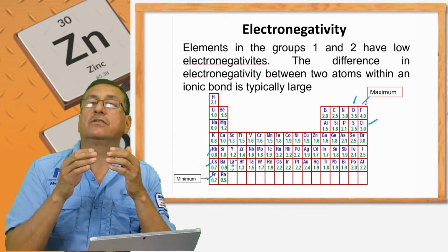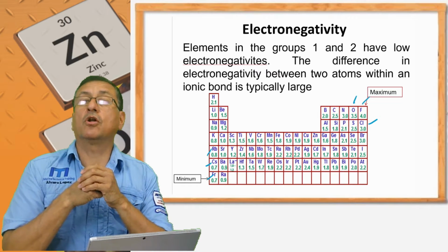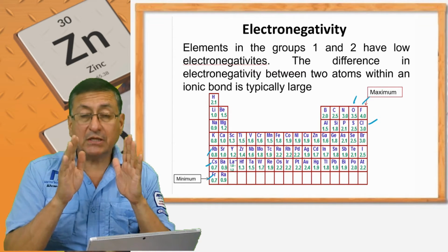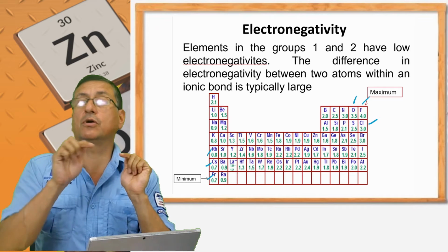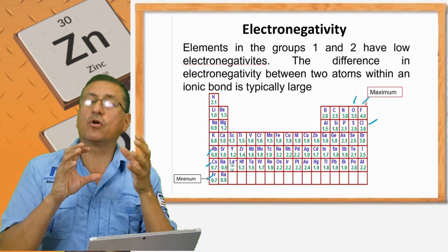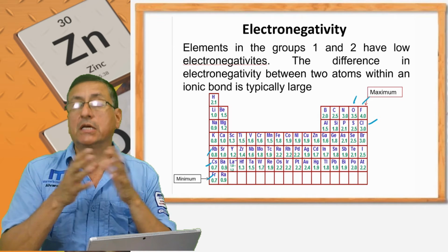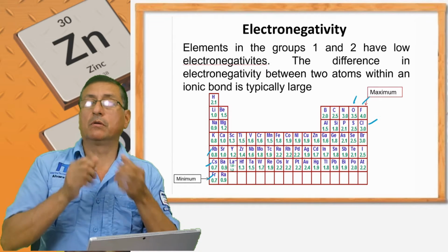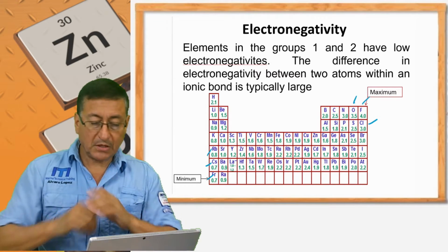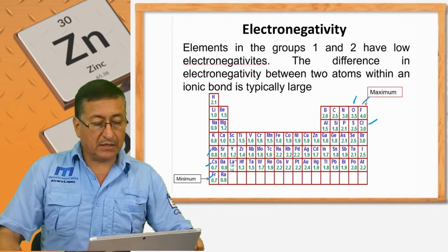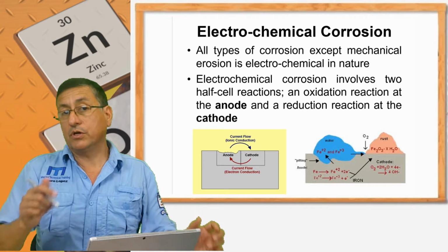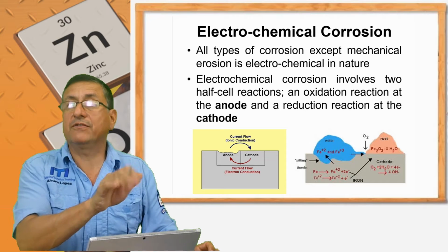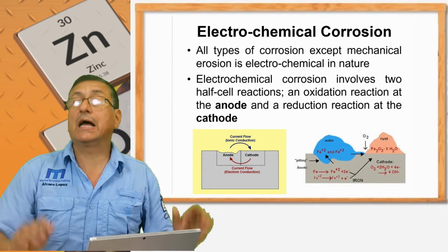The less noble metal is the donor of electrons. The more noble is the cathode, absorbing electrons. This is the situation. It is important that you keep that concept clear, because in this chapter we are going to play with the concept of more noble or less noble. More anodic is less noble, releasing electrons. More cathodic is more noble, absorbing electrons. With that concept, we are going to understand later the process to select the appropriate sacrificial anodes according to the material of the hull and the type of water.